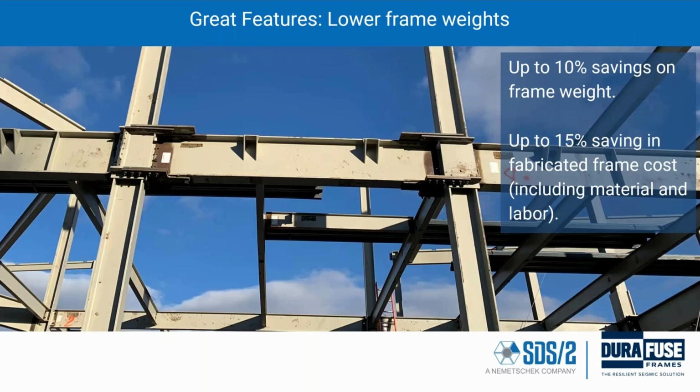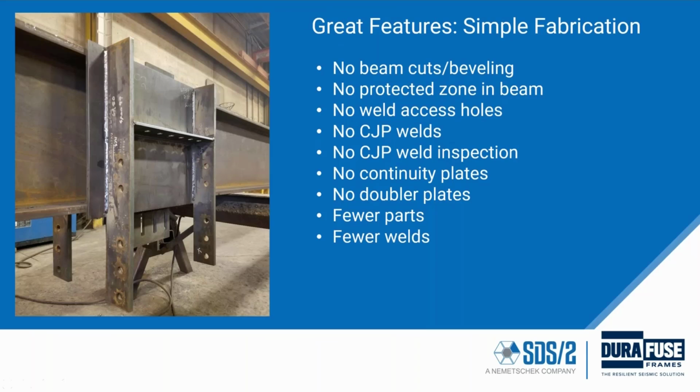Overall frame weights are lower with DuraFuse frames. These cover plates are very efficient in stiffening up the moment frames, which allows us to decrease beam and column sizes compared with other systems. And the fabrication is simple.